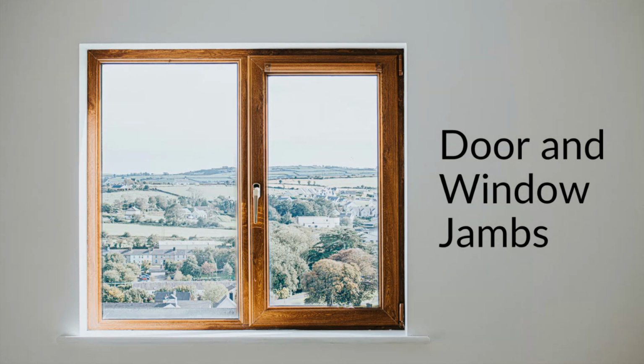And then we would also try to upgrade the wall, because if you just have a basic wall with some metal or hardy board siding and some plywood on the outside and drywall on the inside, that's maybe an STC 36 or 40 or something like that, which is not far off from what the window is. So we want to try and minimize the amount of sound that's coming through the wall, so then we're really just kind of dealing with the window. So sometimes we would use resilient channel or clips and hat channel on those walls, and we would have to deal with the detail of this window inside of it.